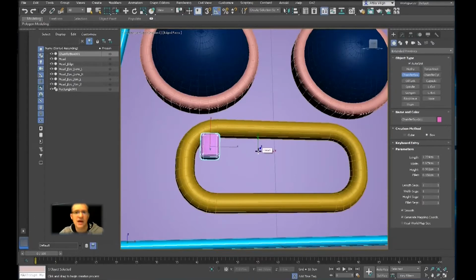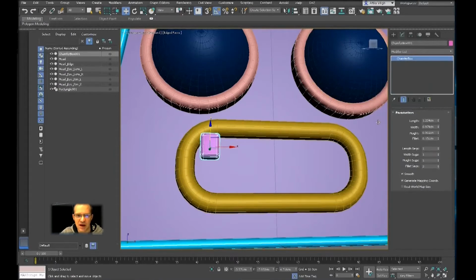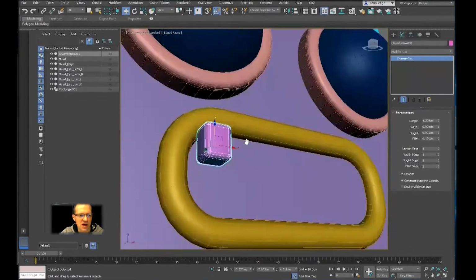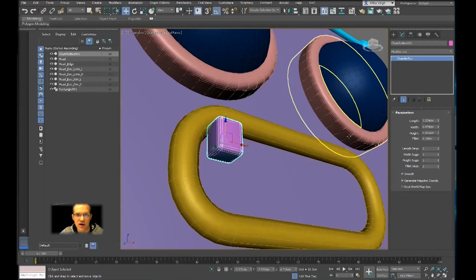If you remember, every time you want to leave a creation method in 3ds Max, you're just pressing the right click. So right click here, and then I'm moving to the modify panel because I want to change the values. Right? So the basic element is here, selected. It has to be selected. And I'm going to the modify panel. It says chamfer box, and this is the fillet value. So if you have accidentally created a basic fillet with 0 value, you only have to go in and try yourself and crank up the fillet. Okay, so that is it.